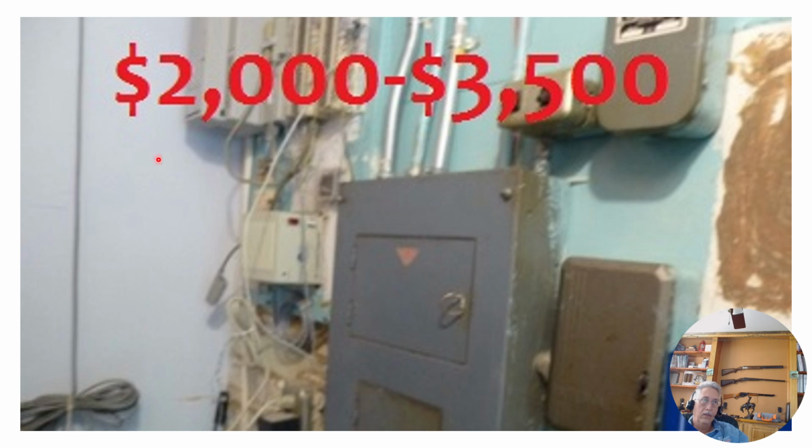Electric service, so this is a, was that a Wadsworth? So I recommended a service change here because first of all it was full, and when you renovate a building, which they were going to do, the first thing you need is more circuits. So around here you could get a service change done with a bigger box.